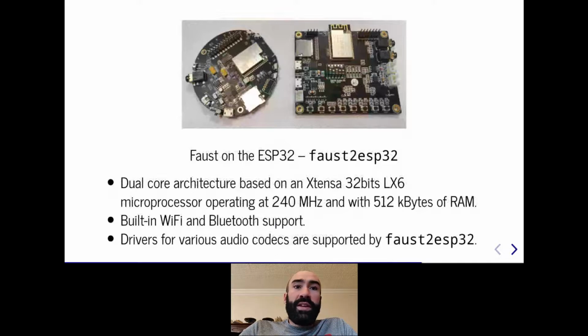and they all can be programmed with Faust through the use of Faust to ESP32. Drivers for various audio codecs are supported by Faust to ESP32 and can be targeted through the use of options when you call that script. Recent developments involve MIDI and polyphony support using the onboard Wi-Fi. OSC over UDP can be implemented, and also Bluetooth MIDI, which is a very recent feature.